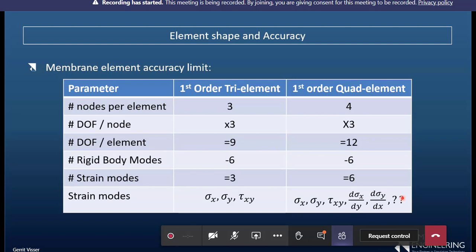So it is probably possible to use it, but this is if you warp it. Think if you have a square section and you move two diagonal points down and the other two diagonal points up, that weird deformed shape, what is the stress state for that? And the answer is there is no real sensible answer, which means that that additional degree of freedom is not that useful to calculate additional stresses.